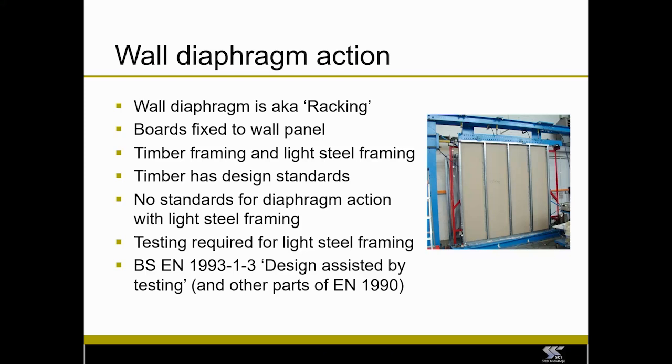It's still within the scope of the Eurocodes, because most of the parts of the Eurocode, so Eurocode 3 Part 1.3, and the basis of all Eurocodes, Eurocode 0 or EN 1990, they all allow for design assisted by testing. So that's what we're utilizing here. We're carrying out some testing, and we're deriving design values from those test results using Eurocode methodologies.